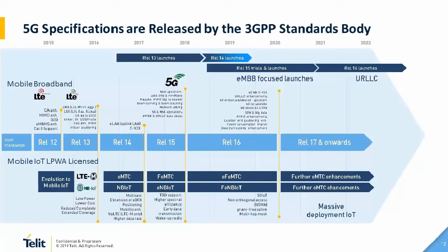And then you get a new technology, massive MIMO, multiple input, multiple output, which means essentially that in the millimeter wave spectrum, it's completely new technology where you can use a lot of communications theory and technology in practical life by deploying, for example, a 64 by 64 array of very small antennas, but they are smart, where you can do individual beam forming and beam tracking from each individual antenna to focus the energy of the wireless signal towards the receiver.